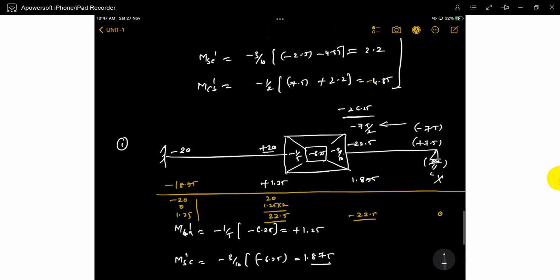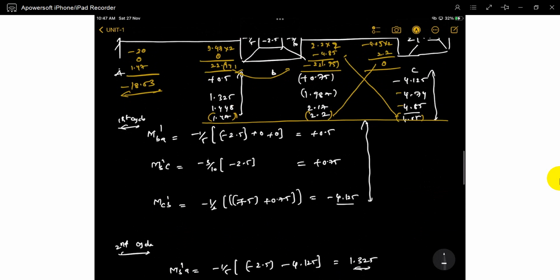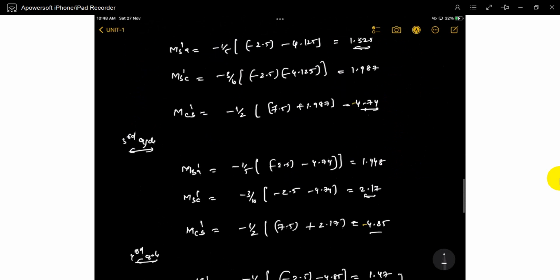You can eliminate any hinge joints at the outer ends. If you can't eliminate, you will do many iterations, because you just increase one extra kinematic indeterminacy, it's going to be somewhat large. Just delete it and you will do it. You can reduce the kinematic indeterminacy. That is the key point. Understood? Got the idea?